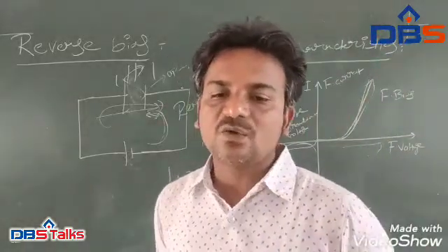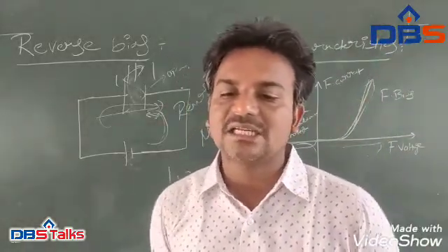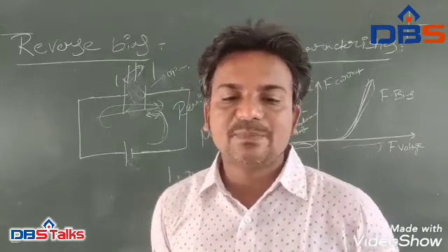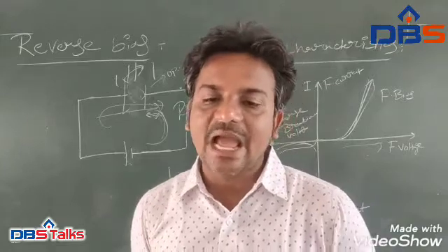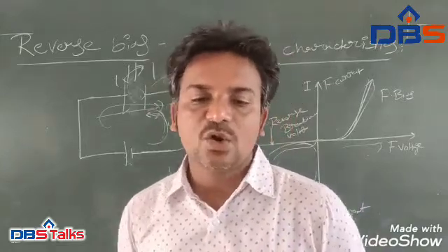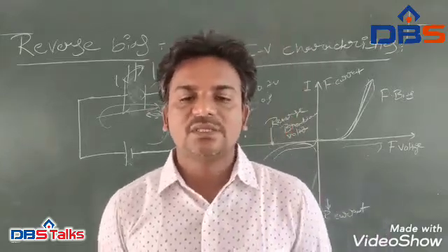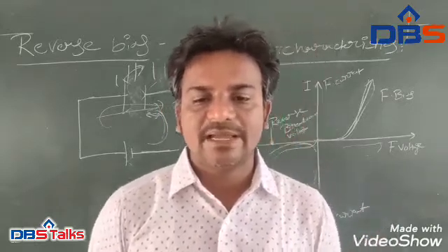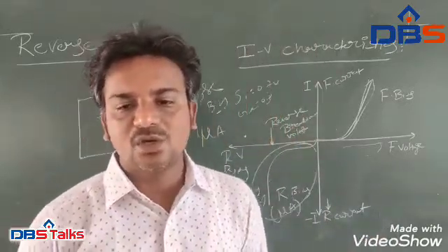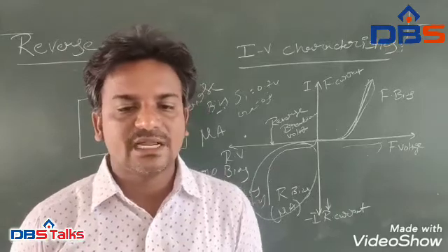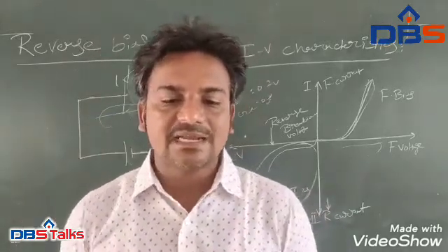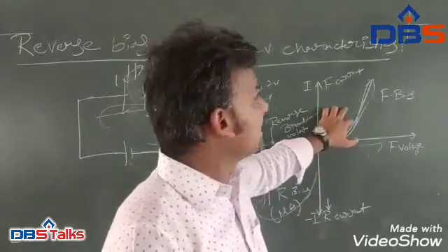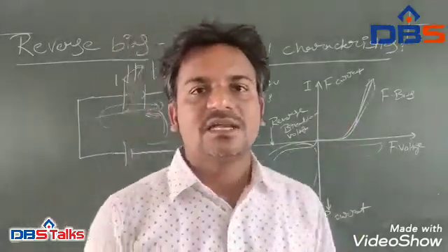So the application of the forward biasing voltage on the junction diode results in the depletion layer becoming very thin and narrow, which represents a low impedance path through the junction, thereby allowing high currents to flow. So this point at which this sudden increase in current takes place is represented in the VI characteristics of the circuit.